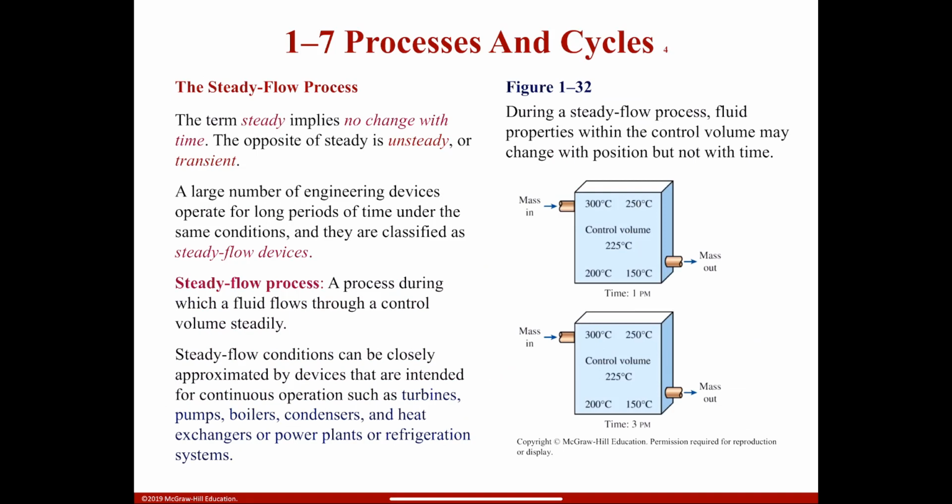Steady flow process. You have to get ready to hear this probably 10-20 times in the semester. The term steady implies no change with time. The opposite of steady is unsteady or transient. A large number of engineering devices operate for long periods of time under the same conditions, and they are classified as steady flow devices. Pumps, turbines, things like that will operate for a long period of time, and that's why they're called steady flow devices.